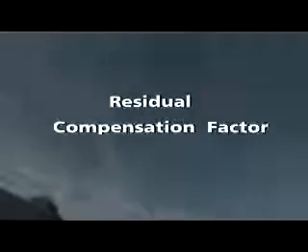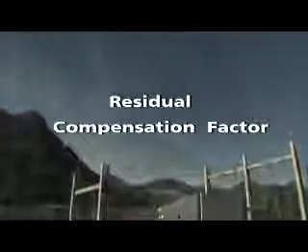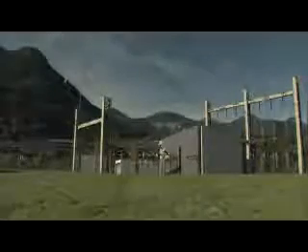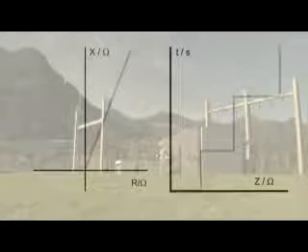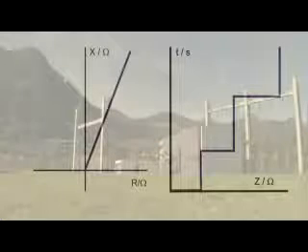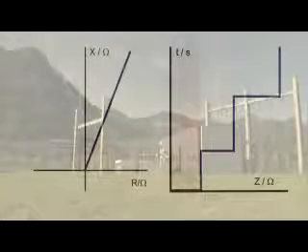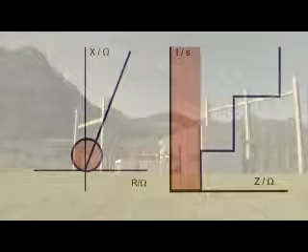Distance protection relays provide fast, selective protection for electrical power systems. The trip decision depends on the distance to the fault and provides protection as selectively as possible. If the relay detects a fault in the first part of the line, designated as Zone 1, it will trip instantaneously. If the fault is further away, subsequent zones provide an additional time delay to allow the relay in the next section of line to clear it first.